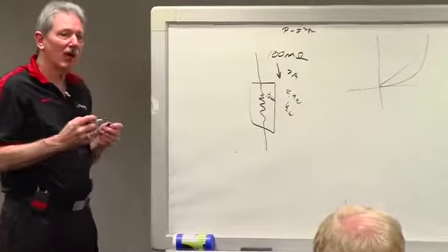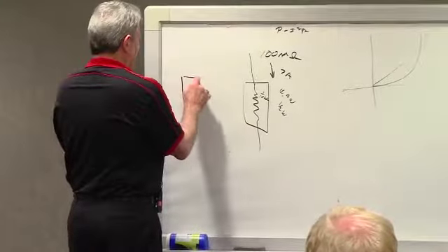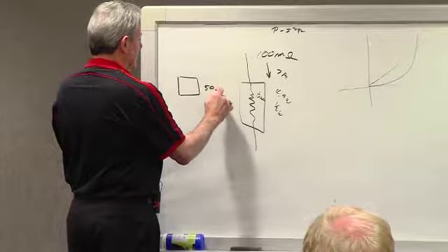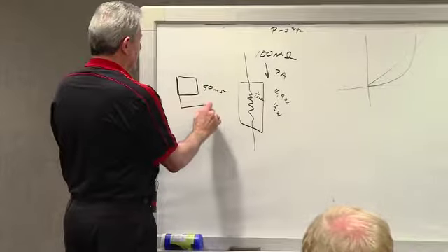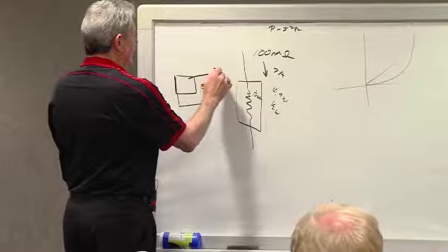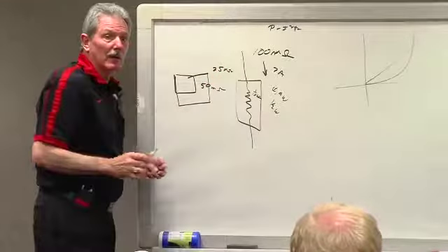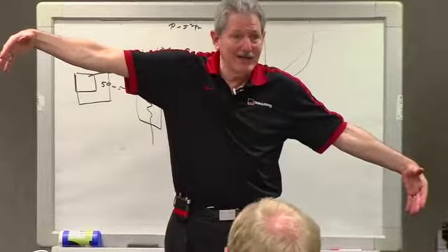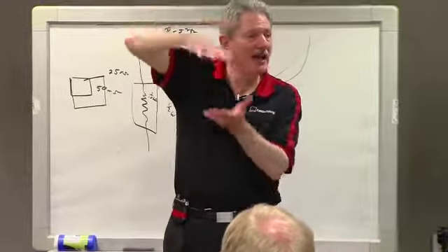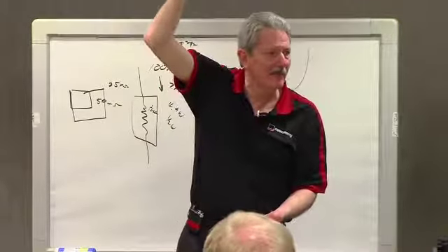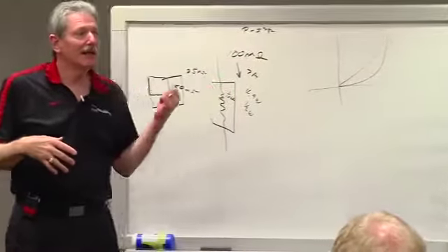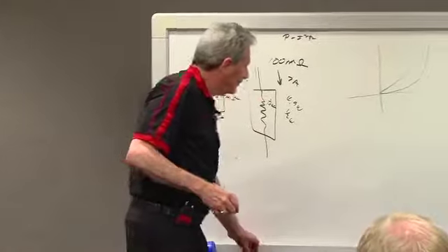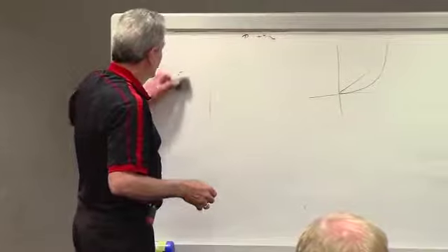The point is, with a MOSFET, if I have a device that big that's 50 milliohms, a device that's twice that big is 25 milliohms. A diode, I can have a diode this big or this big, and it's still 1 volt. The height of that dam is the same. You can't fight that. With a MOSFET, you don't have that. That's the reason why MOSFETs are in all regulators. Here's a problem you got with a MOSFET.